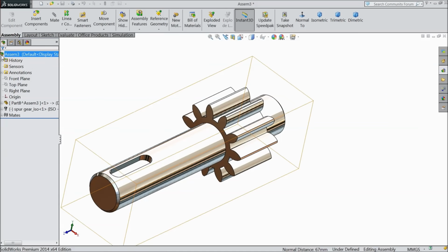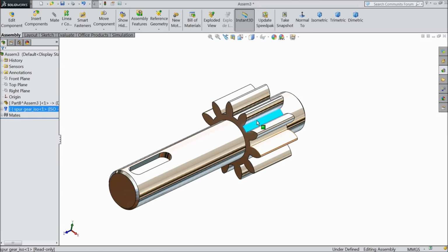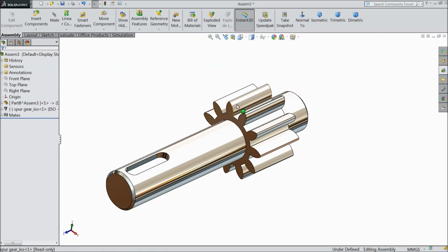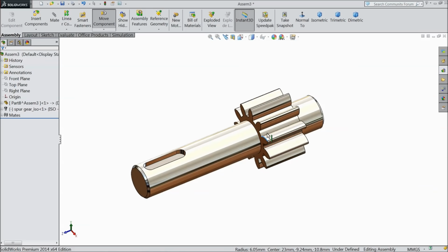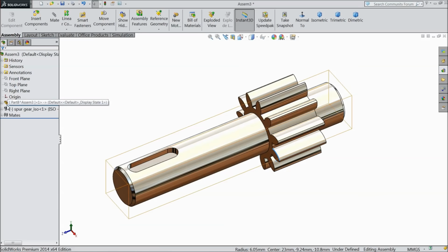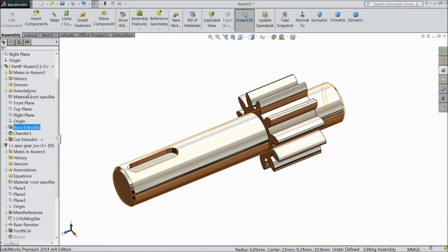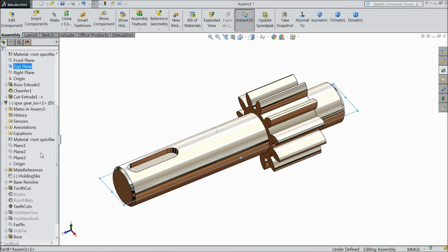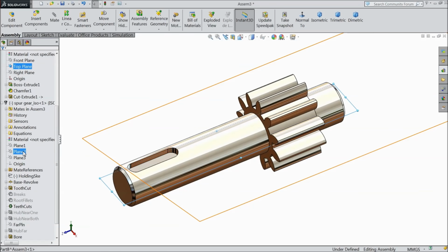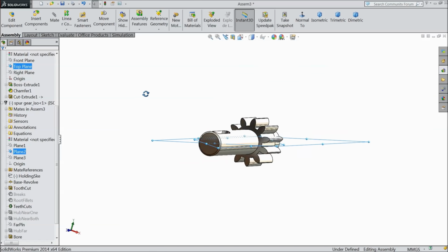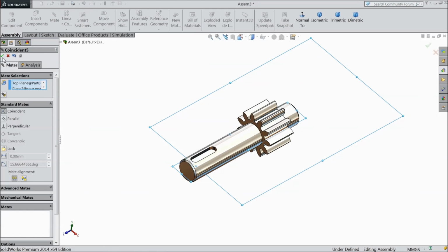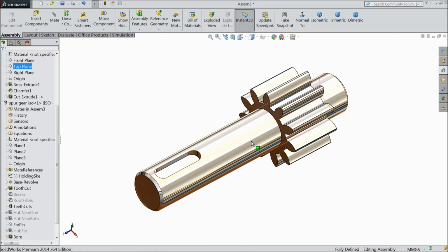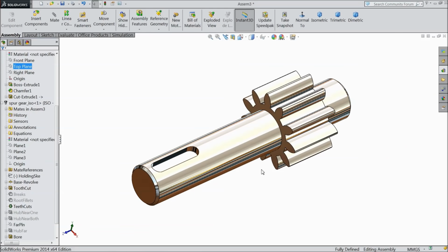OK. Select OK. Now here see the gear is rotating. See, gear is rotating. Gear should rotate with shaft. So we will add some relation. So open shaft, select the top plane of shaft, press Ctrl key and top plane of gear and make relation mate. Now it is fixed. Coincident. OK. OK. Now both will work, rotate together, not separately.